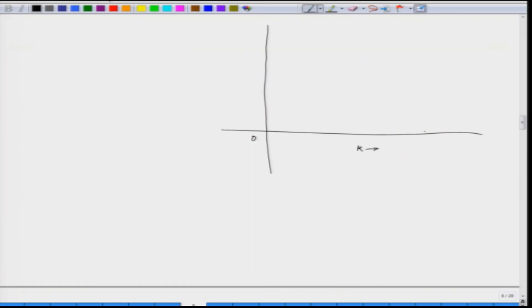in the x axis. So, k is 1 here, and then we have some value of k, maybe equal to 2. So, this is the rated frequency, this is the base frequency. Corresponding to this, the frequency is the rated value. Now, let us see that up to the rated frequency we keep the torque constant. So, torque remains constant. What about the slip speed?